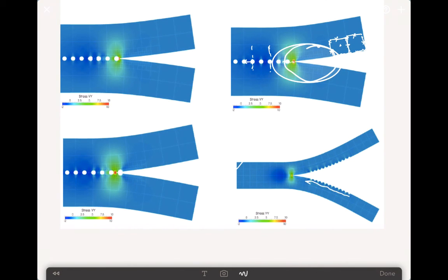to show you these kinds of results is that it's always important, if you have certain crack lengths, because this is the case of a zipper, that these places do not have material, so material has been removed in these areas and these circular parts to make sure that we are going to propagate the crack along this length. So it is going towards the point where you do not have any more material, and therefore it's an easy path to follow.